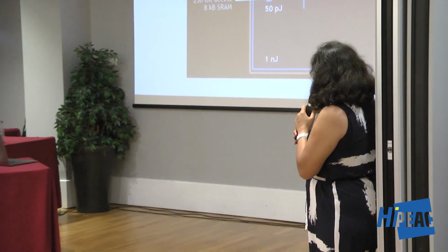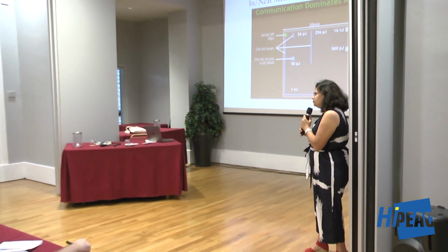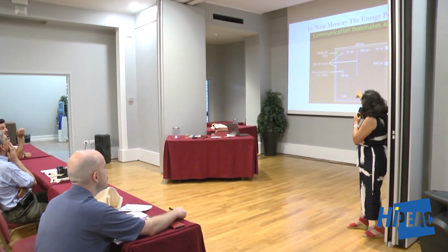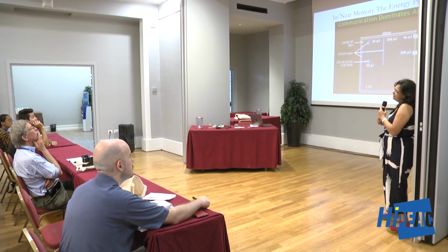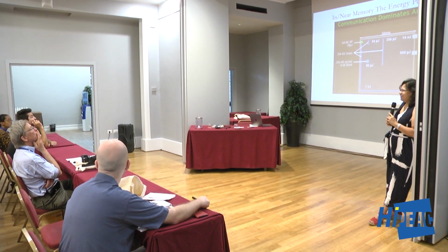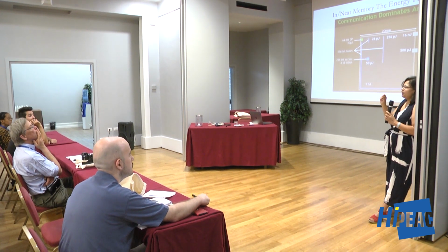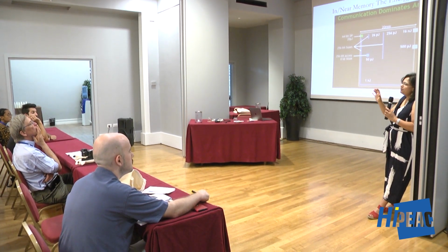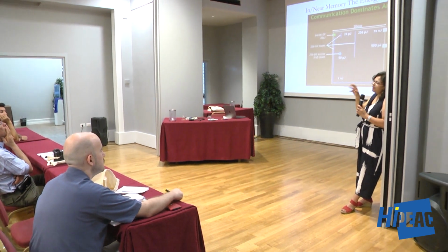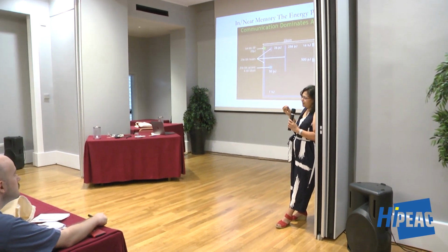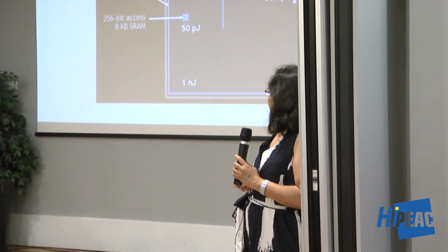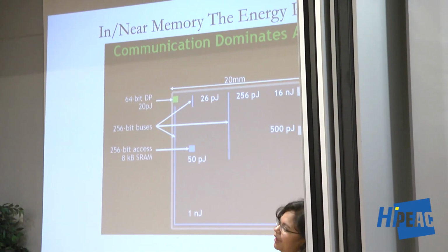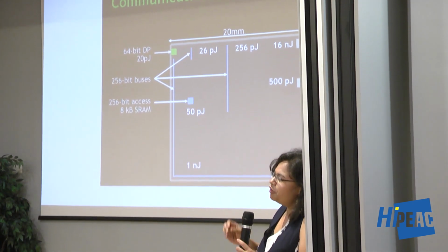Do you have to consume energy for, say, a simple arithmetic like an addition? Yeah, that's that little green thing there. Oh, true. It's so tiny, right? But that's the pure arithmetic, right? When you look at the fetch, the pipeline energy, like the out of order core, that's still expensive, but the actual ALU, it's very tiny. So that's the average, like 20 picojoules for multiplication and addition average? Yeah, that's kind of a rough order of magnitude there.